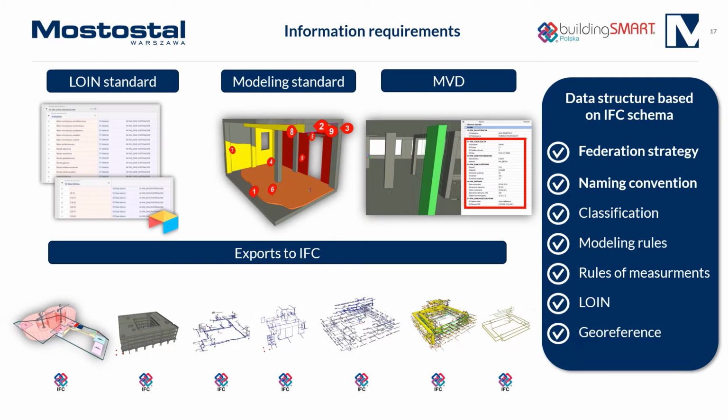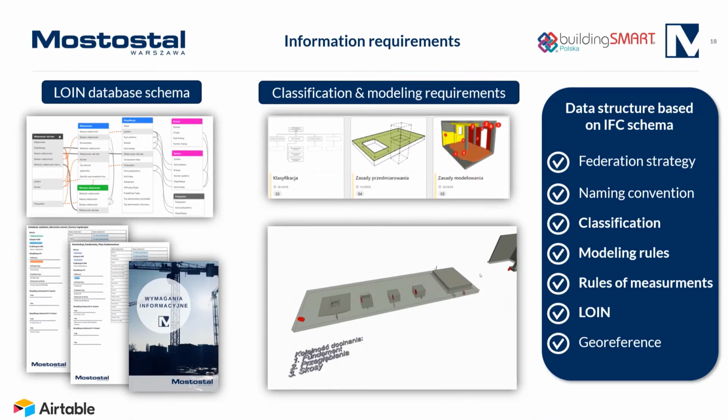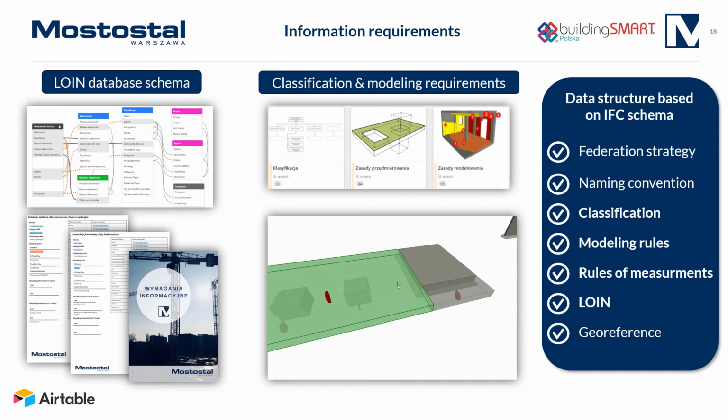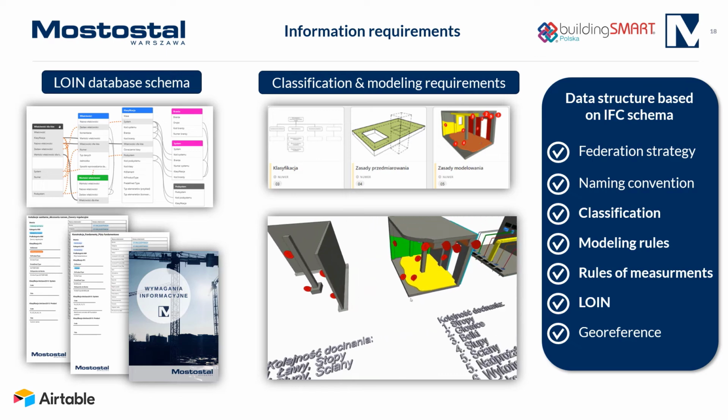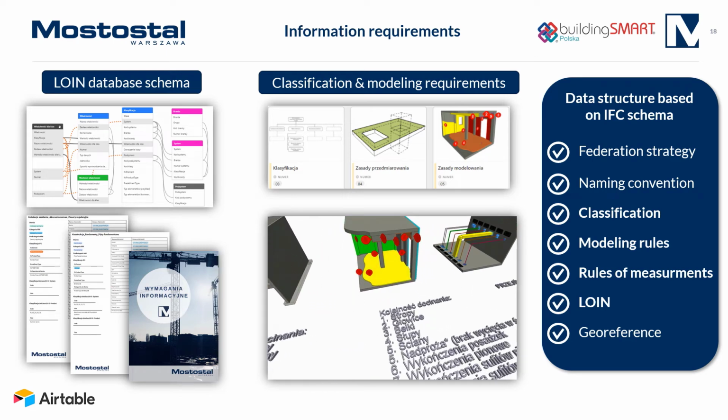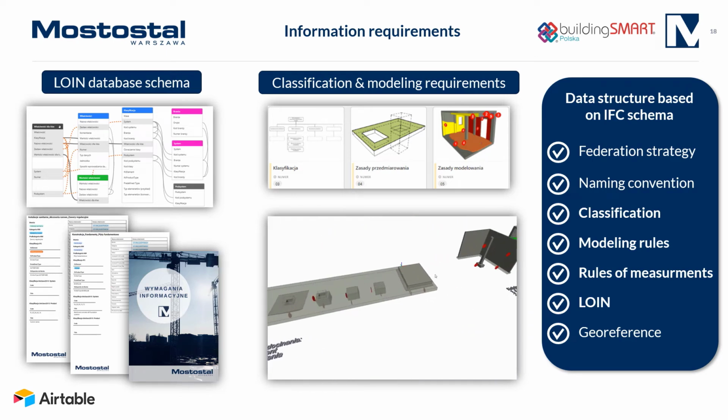Software and information exchange platforms were tested. Working in the openBIM standard made it possible to easily and quickly switch between different software. In order to ensure a smooth exchange of models, the modeling methods and the required information contained in the elements have been defined. IFC helps us to structure the project data through buildings, stories, spaces, and classifications. We also created sample models for the modeling requirements.